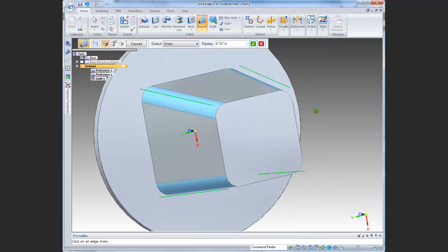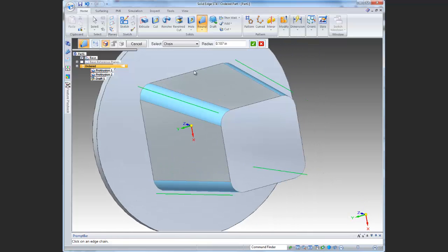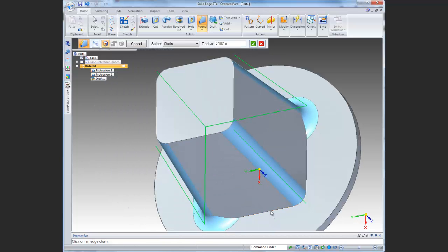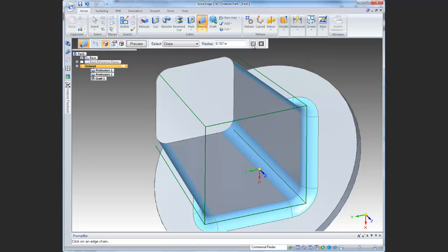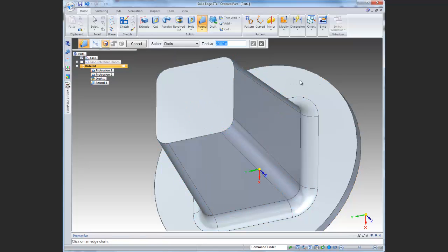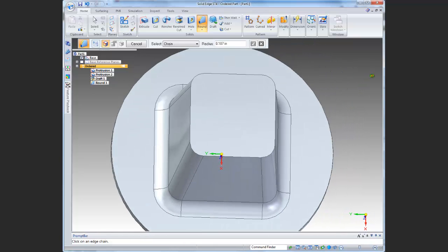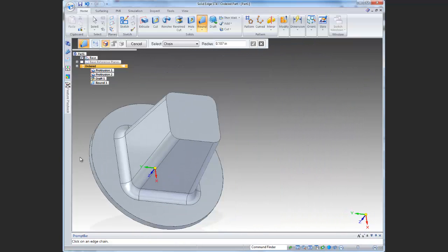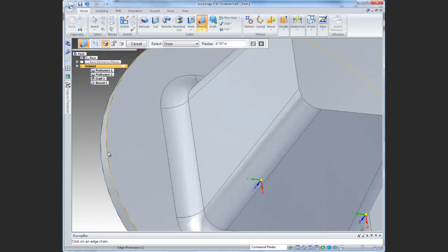And then also for aesthetic reasons, those have to be rounded, right? For aesthetic reasons, I'm also going to choose to round these with the same radius. It will also help us later because since this is rounded from here to here, a chain will smoothly go over this radius, so it will actually help us some in the modeling as well. So I'm going to say check mark to that, and then you can click on preview and finish. It feels like there's some extra steps there. In addition to that radius, I would also like to radius this edge right here.